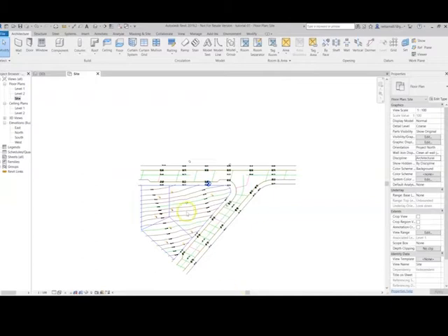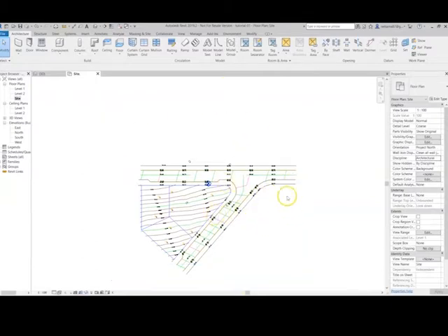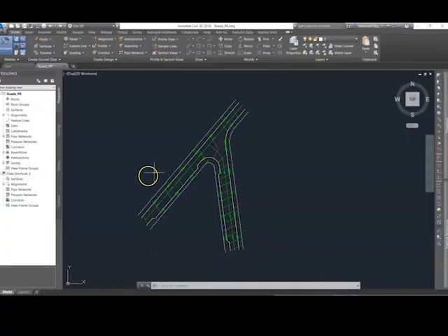So my CAD file is already linked to my Revit project, and I acquired the true coordinates from the survey into the project, and I rotated the project north to make the view more convenient. To export a CSV file, I will work on Civil 3D, but this command also works on AutoCAD. The CSV file we want is basically a table containing information of the elevation points. To each point, 3 parameters: x, y, and z coordinates, or northing, easting, and elevation.